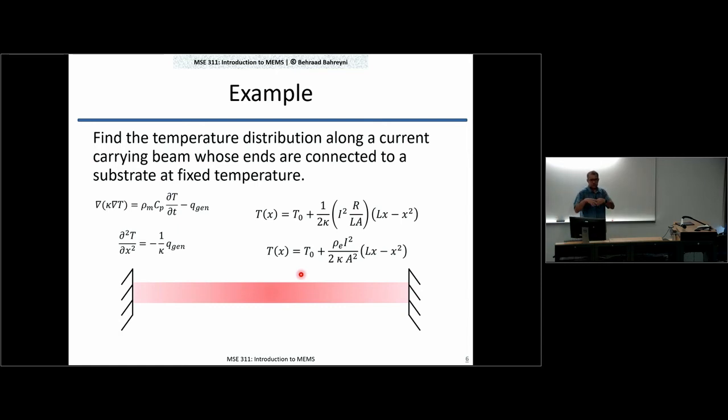The rest of your chip and the package and everything else behave as a heatsink. So in most situations, you lose the energy very quickly to this heatsink through conduction. Convection is, well, there is convection, of course, but it will be much, much smaller than the amount of heat transferred through conduction. For most situations, we do not really take convection into account.